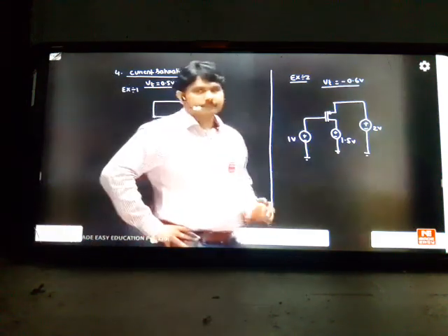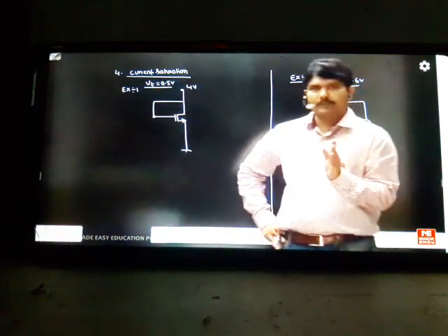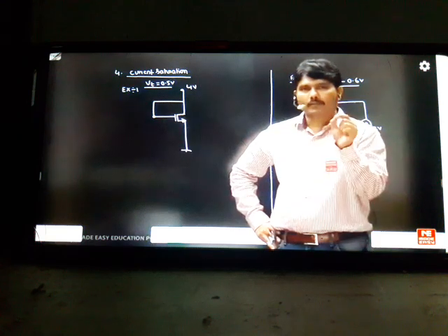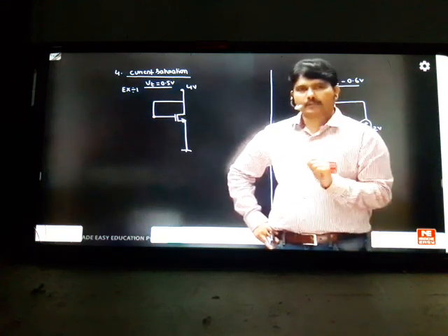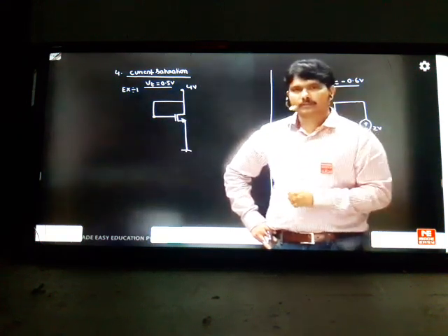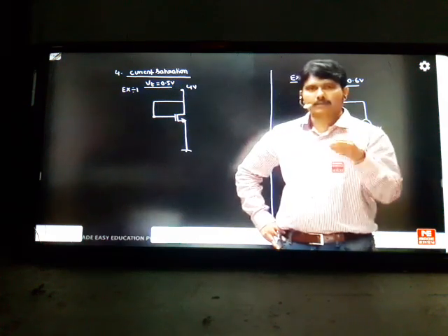Somebody does the cutoff area now. If the VDS value is not 0 volts, say millivolts or volts, they'll try to give the options clearly: ohmic, they'll not do triode. If they give triode, they'll not do ohmic. They'll clearly mention that. They'll not confuse you by doing both. Otherwise, particularly they'll use the 0 volts VDS value to tell that it's ohmic directly.